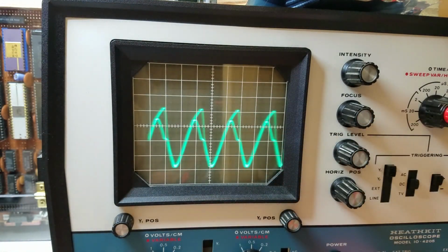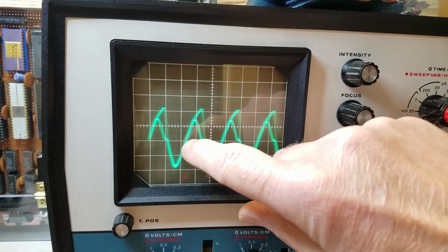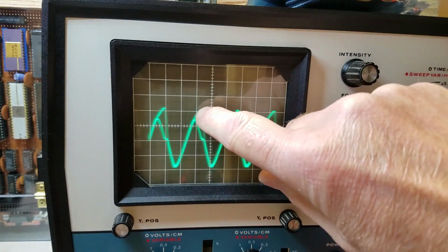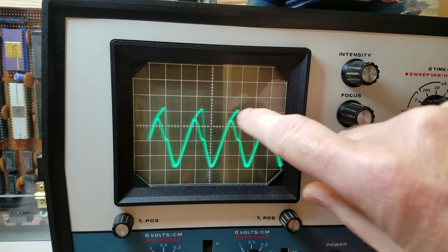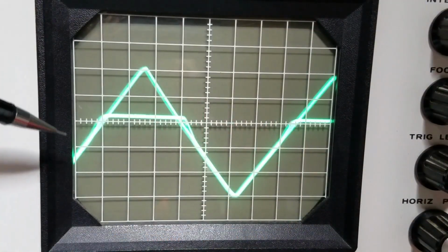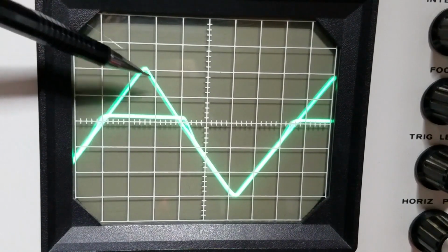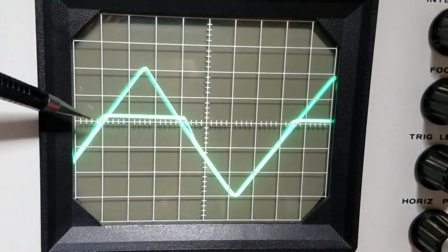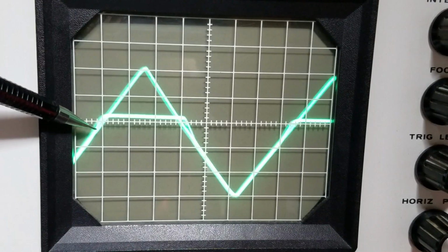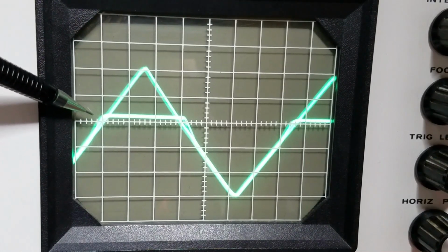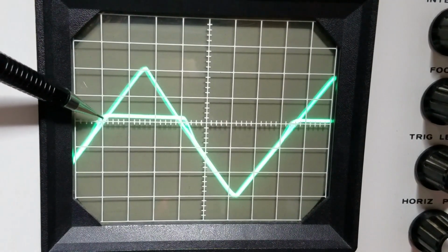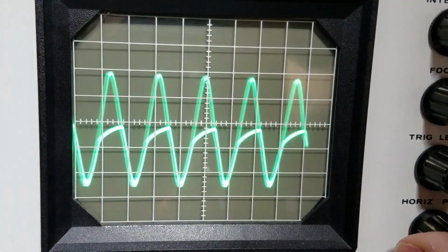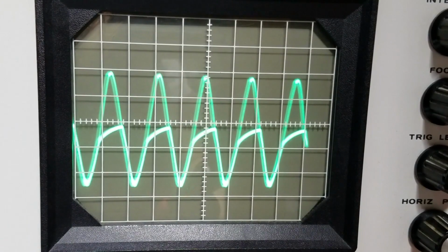Finally, I ramp up the frequency to 250 kHz, which exacerbates the slow rise time, but then there's a lot of capacitance from my oscilloscope leads. To test the low-level output, I feed a 5 volt triangle wave at 7000 Hz into the high-level input. If you look closely, you can see the effect of the body diode on the low-level output. As I increase the frequency to 250 kHz, the rise times for the low-level signal continue to look acceptable.